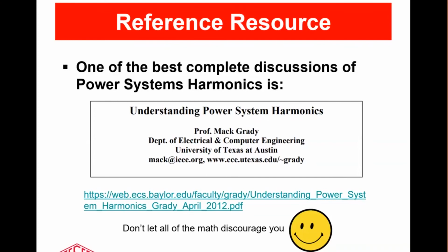And since back at the power station, it's almost certainly true that all of that wasted energy has been filtered out by the network, you're buying VA that's very close to kilowatts. And then you're allowing the customer to use kilowatts that are nowhere close to the VA because of the losses that he forces onto the system.